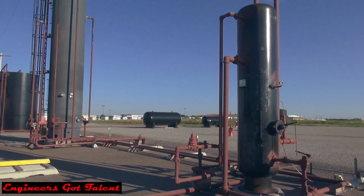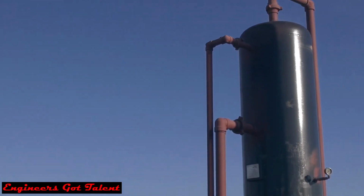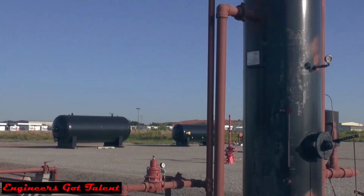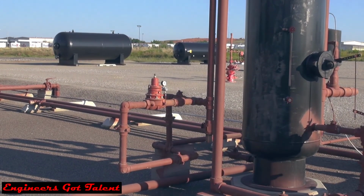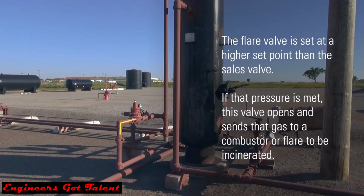A second valve that's related to the sales line is what we refer to as the flare valve. The flare valve is installed in case of maintenance on the sales line, or in the wintertime a line could possibly freeze, or further on down the line they may be tying in a new well and pressure backs up on the existing location. What the flare valve does is set at a higher set point than the sales valve. If that pressure is met, then this valve opens up and sends all the gas that used to be sent to the atmosphere. It's now sent to a combustor or a flare to be incinerated until the condition changes.